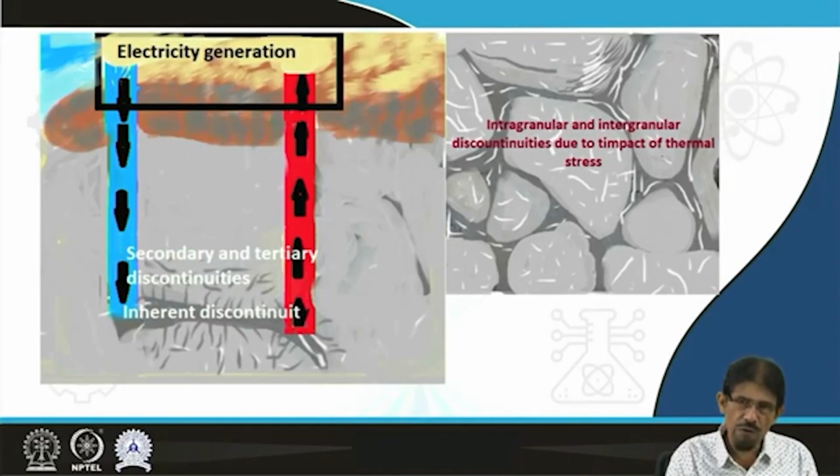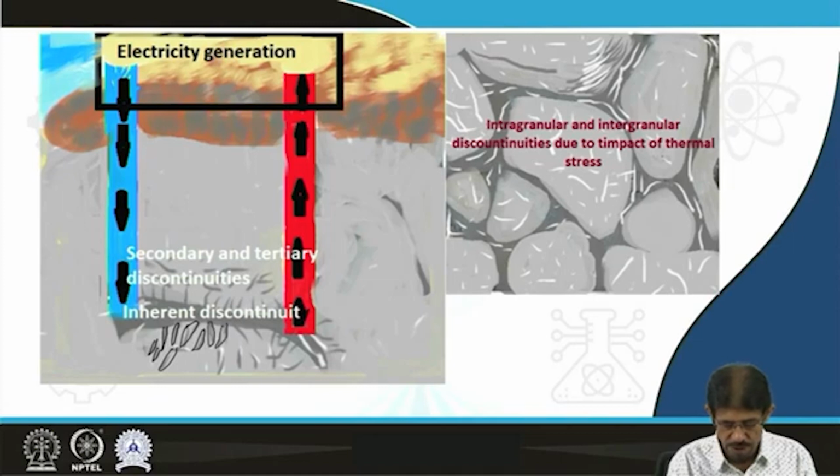In view of the mechanics, when we inject the water, it first reopens the inherent discontinuities like fractures and cracks present in the reservoir. Besides the increase in aperture of the discontinuities, the injected water-induced pressure is responsible for the formation of some new discontinuities, new fractures also.